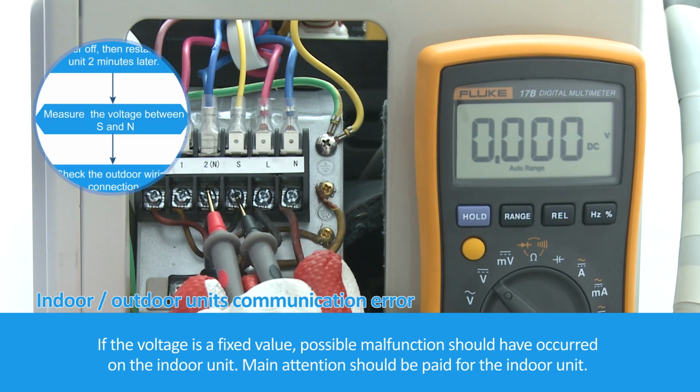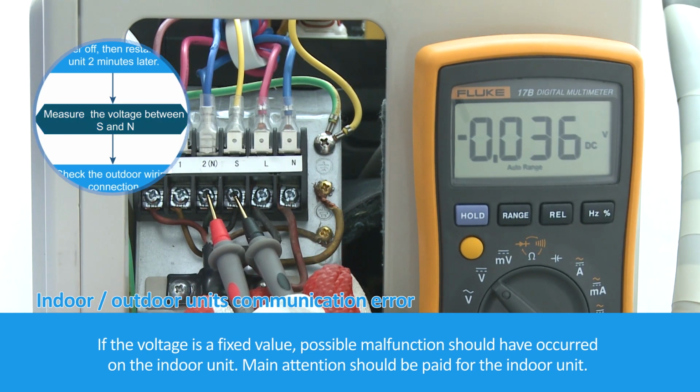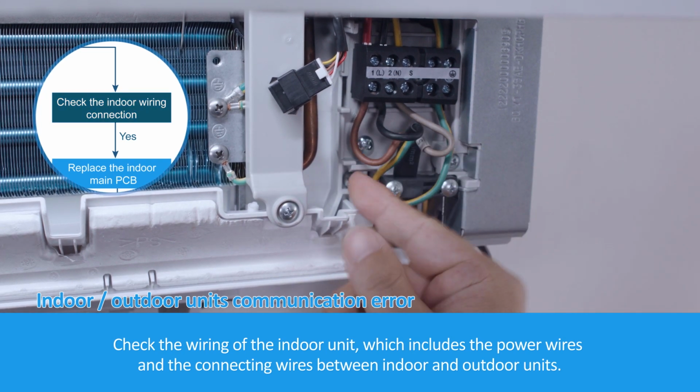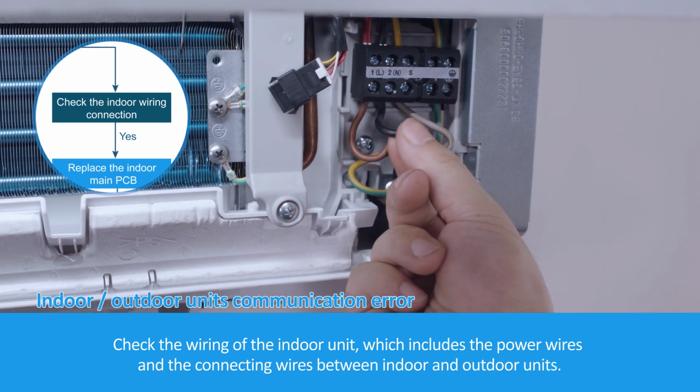If the voltage is a fixed value, possible malfunction should have occurred on the indoor unit. Main attention should be paid for the indoor unit. Check the wiring of the indoor unit, which includes the power wires and the connecting wires between indoor and outdoor units.